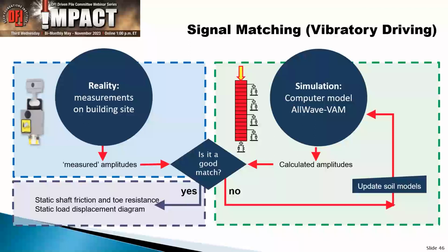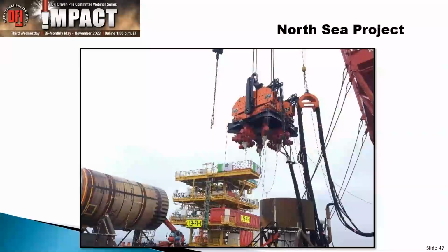One quick comment on that. Quite often I show here the picture of the same strain gauge and accelerometer. The strain gauge, generally speaking, is no problem. You can generally use the same strain gauge you can use for impact driving. Your accelerometer is slightly different because the frequencies are so much higher. Therefore, the forces on that accelerometer are a little bit higher. You may have to use a different accelerometer, but the principle is exactly the same.